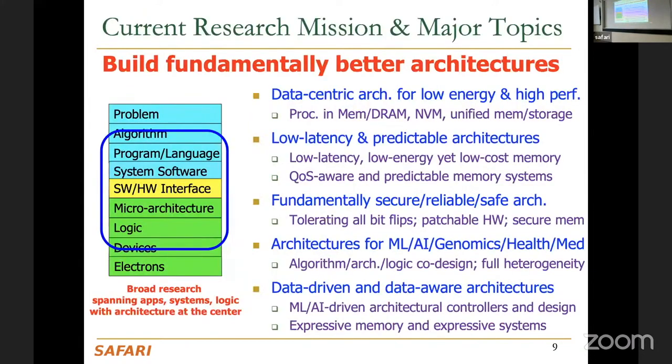Okay, so this is a very busy slide that talks about, maybe in more detail, what we do. I'll go through these relatively quickly, but we're very interested in emerging non-volatile memory technologies like phase change memory and RRAM, unifying memory and storage using a single interface so that you can get rid of a lot of inefficiency in data management in existing systems. If you look at existing systems, you have memory and storage, and they're managed completely differently, right? You have to move the data between storage and memory. Can you actually have a single unified view of memory and storage?